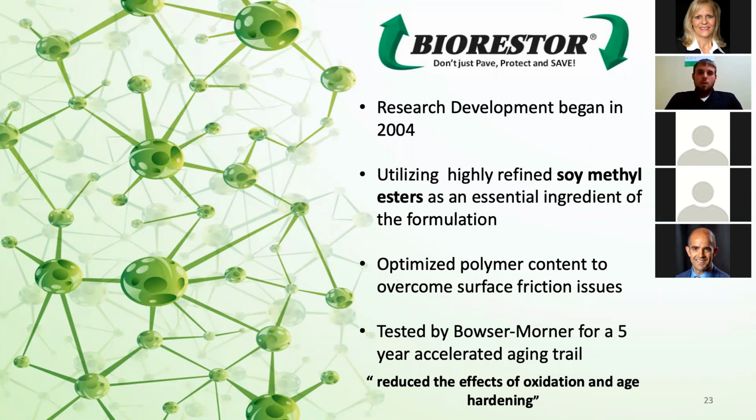So BioRestore started research and development in 2004. It utilizes a soy methyl ester as an essential ingredient. We optimized the polymer content when it was being developed to really overcome the friction issues that many rejuvenators have. It's long known that rejuvenators diminish the friction value initially, but we take it very seriously to try to get those friction values back to a safe value for the traveling public.